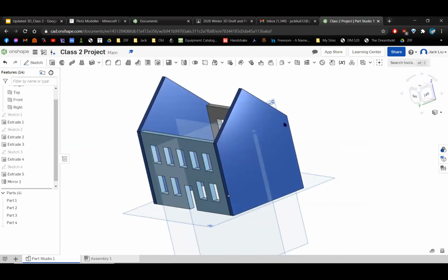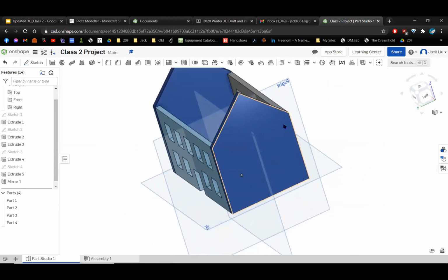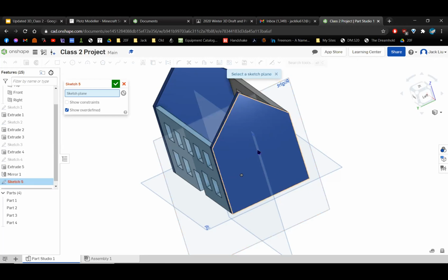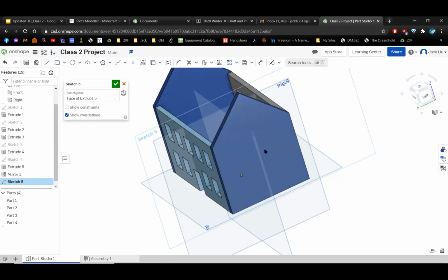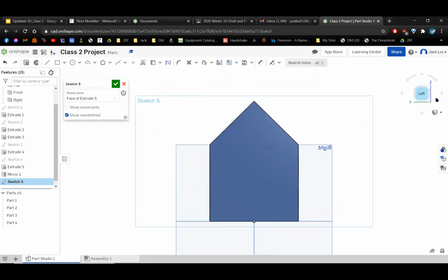But first of all, how are we gonna do this? Well, we're gonna create the side profile of the roof. And so we're gonna create a new sketch on the side of the wall that we just created. Right? It doesn't really matter left or right side, but just one of them. So I hit new sketch, and I'm gonna draw the sketch on the side of the wall that I created, right? And then as always, I'm gonna reset my view so I can do right click, view normal to sketch plane, or use the cube to click the surface I wanna look at. But now I'm looking at the side. So what does the roof look like when looking at it on the side? Well, it's gonna be kind of like two slanted rectangles.